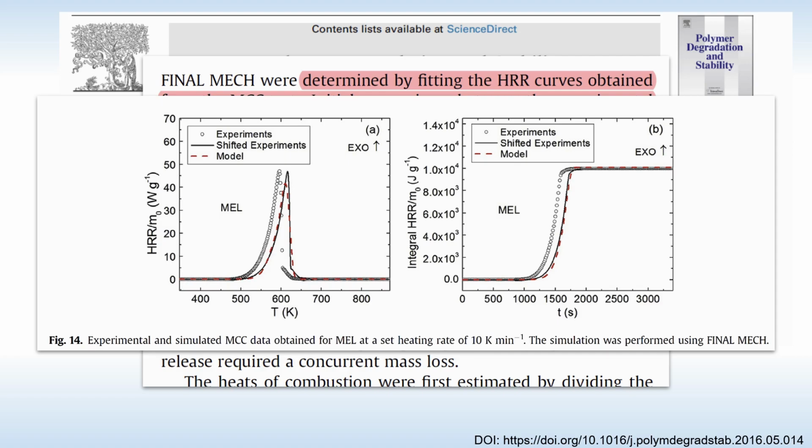In the MCC, there is a pyrolysis chamber in which the sample is located and a combustion chamber above that. The presented idea is that the combustion chamber above the sample is operated at high temperature. From there, extra thermal energy is reaching the sample from the top.